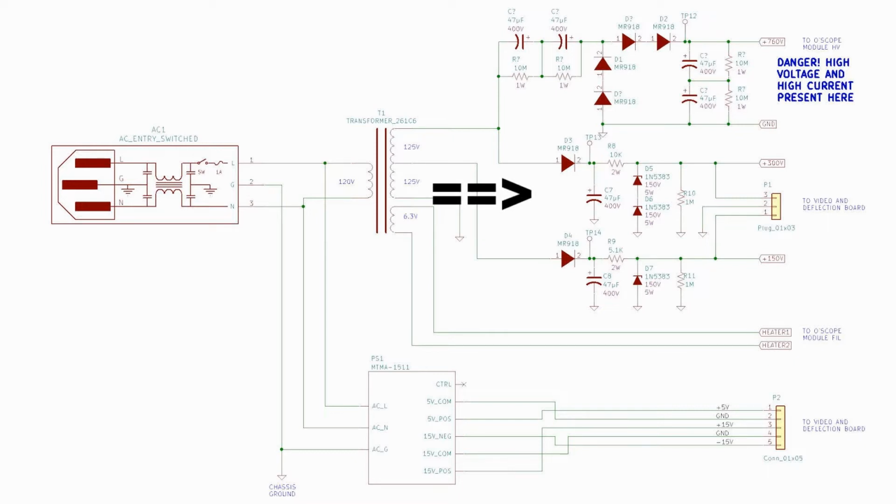Moving down to the next DC power supply, we have a half-wave rectifier into another 47 microfarad 400 volt capacitor. After rectification, that capacitor has about 380 volts on it. We drop the voltage to 300 volts with a pair of 150 volt Zener diodes and limit the current through a 10K 2 watt resistor. The 300 volts goes to the deflection circuits.